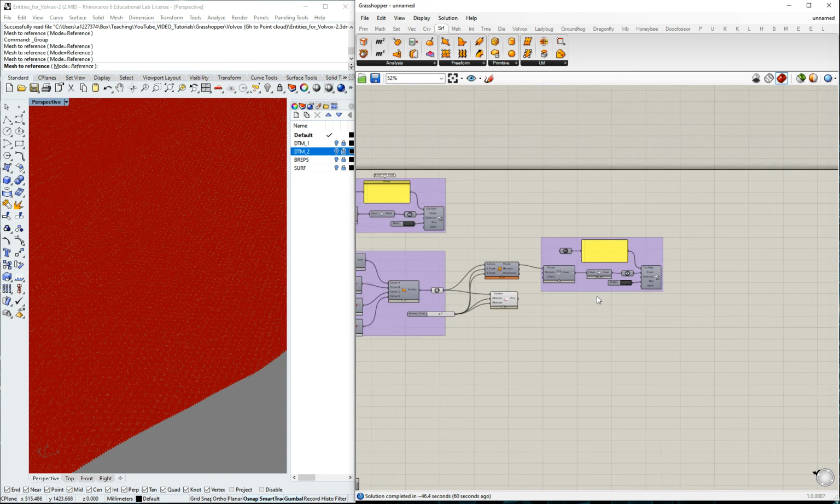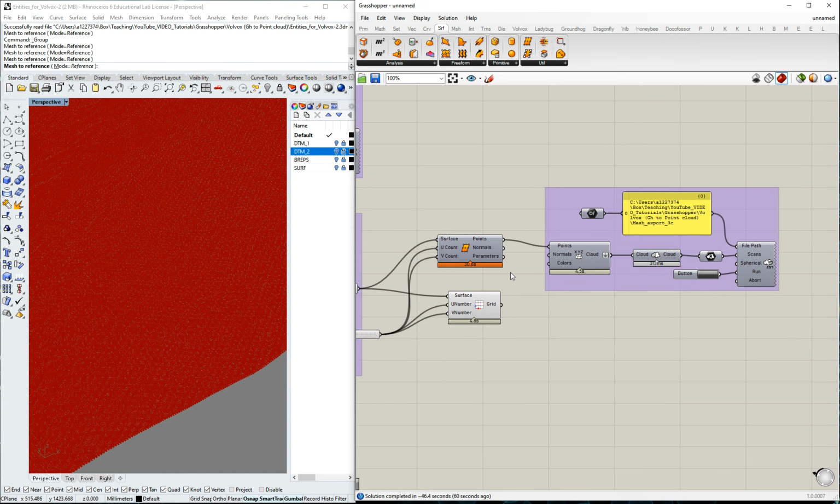Okay, remember that. Now we're going to export it as a 3C, and it's taking longer because the number of points is much denser. So you can control the size of the triangulation, the size of the mesh for the triangular regular network, the complexity, the regularity by exporting or preparing the mesh before. You can control the number of U and V's, I mean the distribution of elements in the surface, and then export everything. So there are many ways you can control the density.